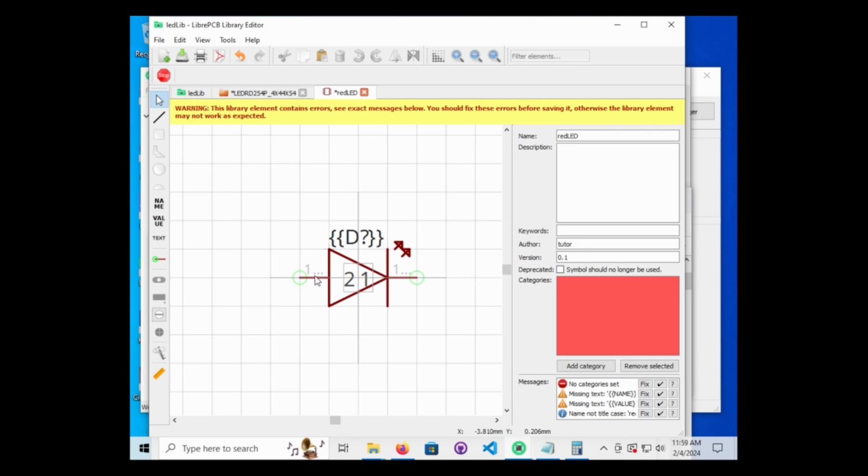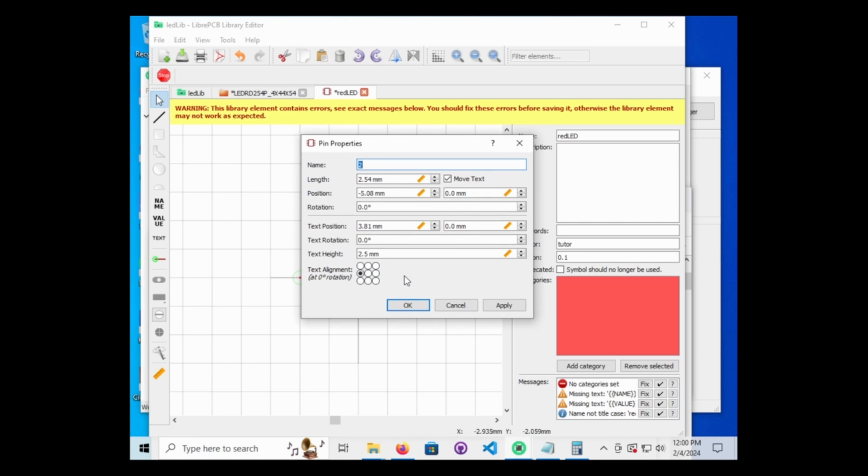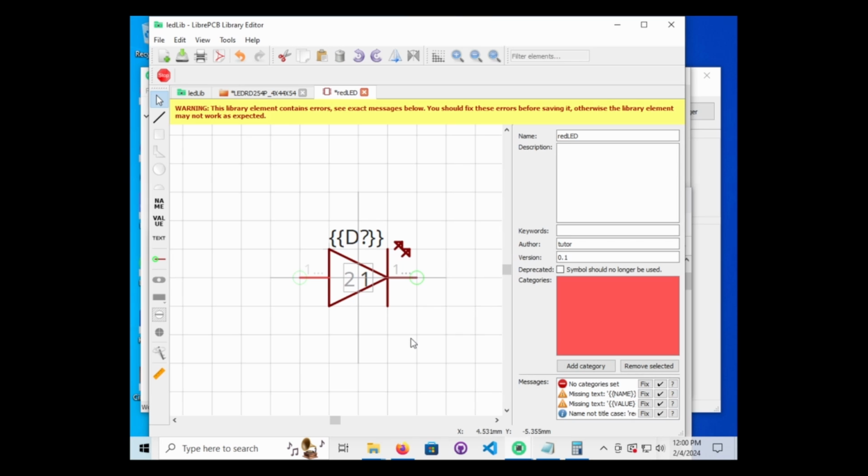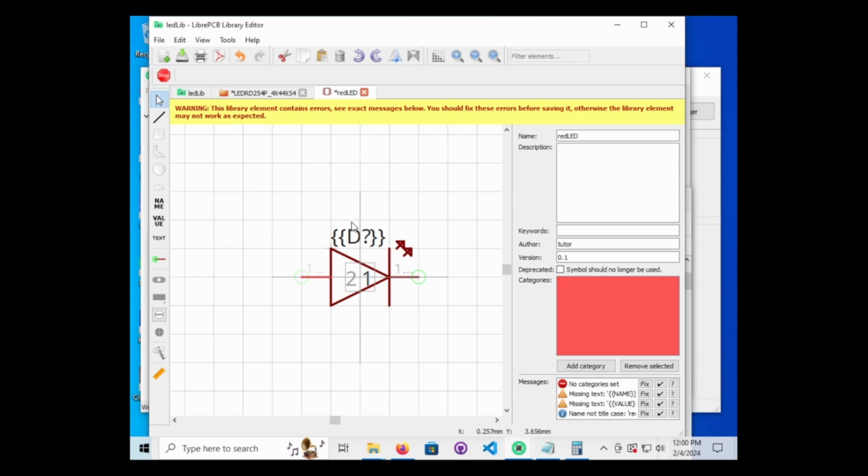Now, when you're creating a schematic component, usually you just leave the default as value with the extra curly braces, because usually it'll be filled out. You'll place the components. It should have something to increment itself, so it'll be like D1, D2, D3. And then you can input your own particular values. Some people like to have their library where each one has its own thing.